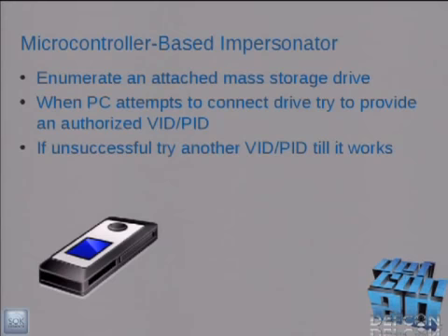All right, so how does this microcontroller-based impersonator work anyway? What it does is it allows you to insert your flash drive, and it enumerates it. And then when you plug this device in the PC, it says, oh, I see there's a new device. Let me enumerate it, and it tries to get an authorized VID-PID combination.